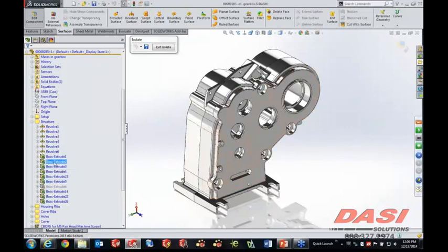But if you just simply pause while you're panning over top of one of these features, these reference indicators are going to pop up automatically. Now, it used to happen immediately in beta, so we've put a little pause on it now, but as you hover for about a second and a half, you'll see this parent and child scheming show up here. Now, some of these arrows actually show with names. If I look at Boss Extrude 2, for example, you see the arrow going low, shows motor floor, but it's pointing to Boss Extrude 3. Well, the motor floor happens to be the sketch that's absorbed by that feature, and if that feature was shown, then that arrow would not indicate the name of it since it's not buried beneath another feature.